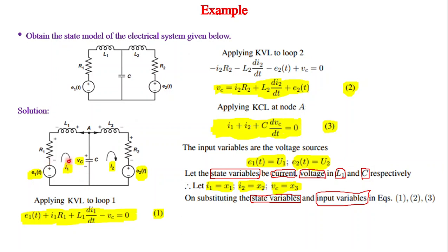So first we have to do the circuit equation modeling, right? So we have to apply proper laws. We can apply KVL as an illustration. Here what I have done is branch currents are assumed. Here one branch current, here one branch current, here one branch current. That is why this is plus, this is minus, this is plus, this is minus. Where the current enters is plus, leaving is minus. Similarly here for the other elements. However, for the purpose of writing the equations, loop currents are used. So I1 in clockwise direction, I2 in clockwise direction.